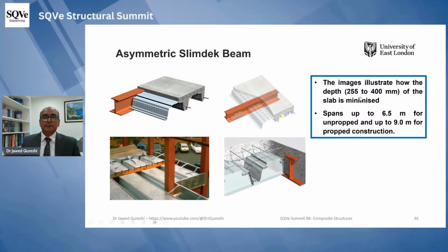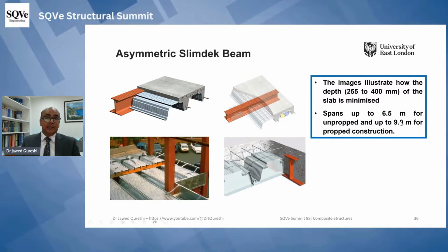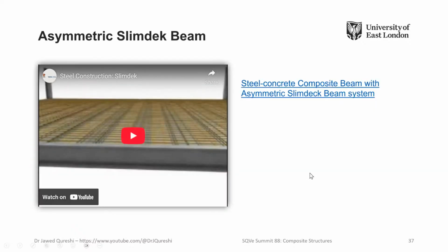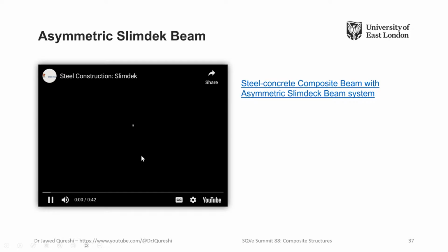And here the depth is 255 to 400 millimeter overall, and it can span up to 6.5 for unpropped construction and up to as much as 9 meter for propped construction. Now, what is ASB? I will play this video here.